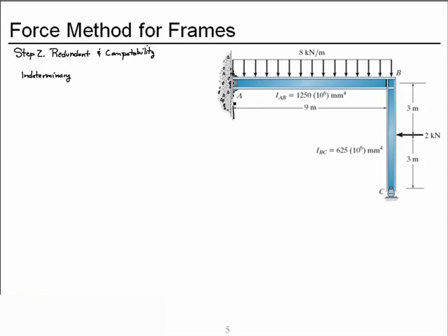Well, we have a vertical reaction at A, a horizontal reaction at A, a moment reaction at A, and a vertical reaction at the rocker, which means we have 4 unknowns. From that we subtract the number of free bodies, 1, 3 equations of equilibrium for that free body, and we get 1 degree indeterminate, which means we need to choose one redundant.